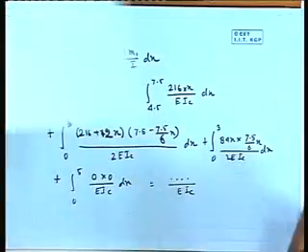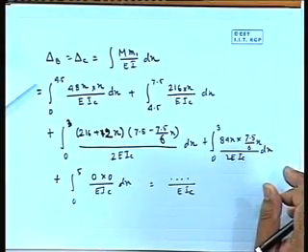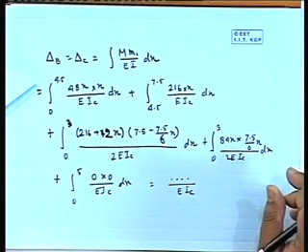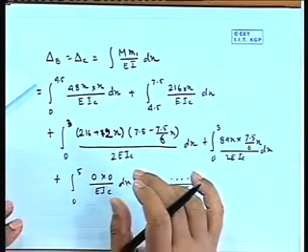So there we are getting the effect of actual load, and small m, the structure is entirely free from load, just 1 unit load applied, we are getting another set of moments. So both the effects we are combining as capital M small m divided by EI into dx. Through integration we are getting the value.